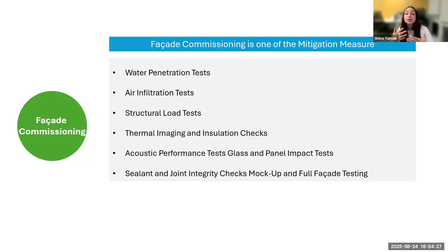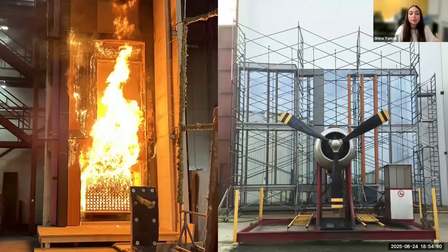But again, the moment of truth, the testing, is the only thing that can actually say if this facade system is succeeding or not. It happens a lot. We saw leaks. Okay, what can we do? When there is a water leak, we disassemble, we detect where the leaking is happening, we try to rectify it and install again. So too many tests can happen.